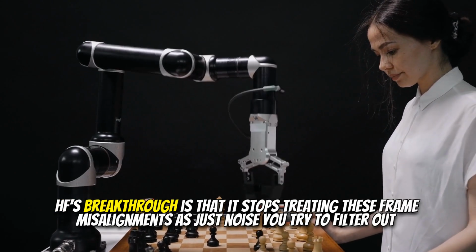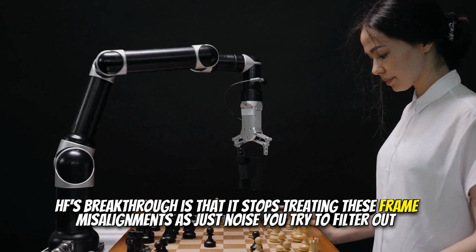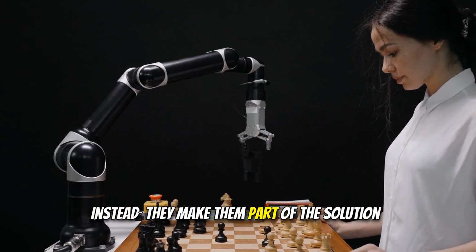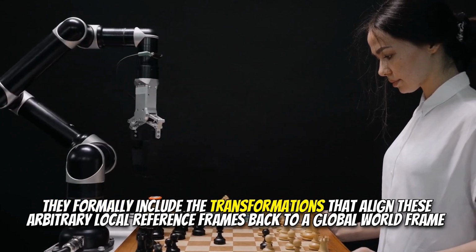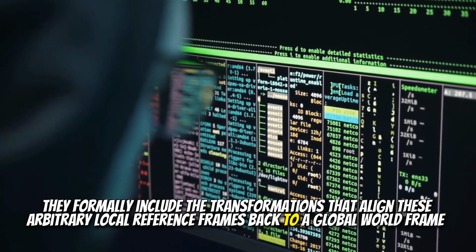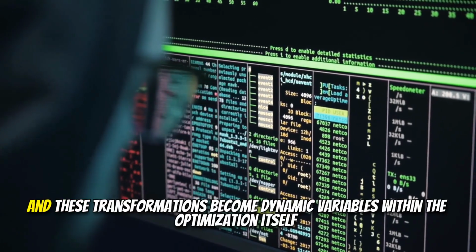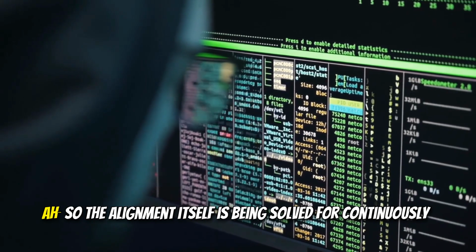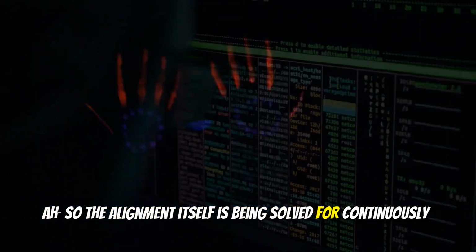Right. HF's breakthrough is that it stops treating these frame misalignments as just noise you try to filter out. Instead, they make them part of the solution. Exactly. They formally include the transformations that align these arbitrary local reference frames back to a global world frame. And these transformations become dynamic variables within the optimization itself. So the alignment itself is being solved for continuously.